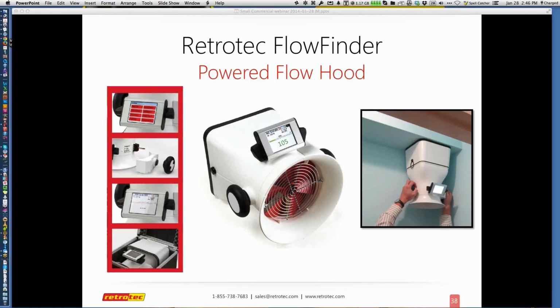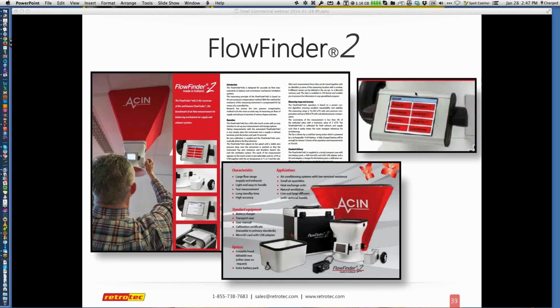It's a device that we're getting in the hands of various trainers, and we've sold a number of them to people that are using them to measure HRVs. I think it's one of the best in-home diagnostic tools you could use, and it will do zero balance up to 323 CFM and compensated flow up to 500 CFM, and goes all the way down to, I think, 4 or 5 CFM. It's a nice piece of equipment, and we think it will prove itself to be an amazing tool out there. I look at it as being an MRI.